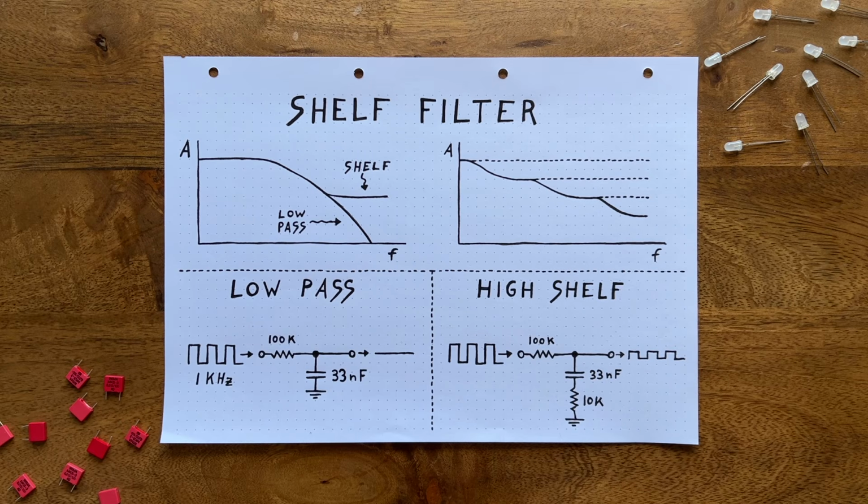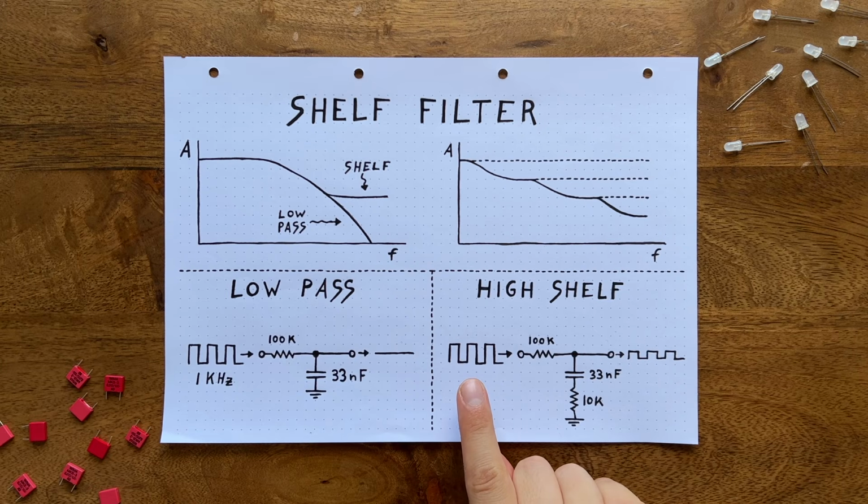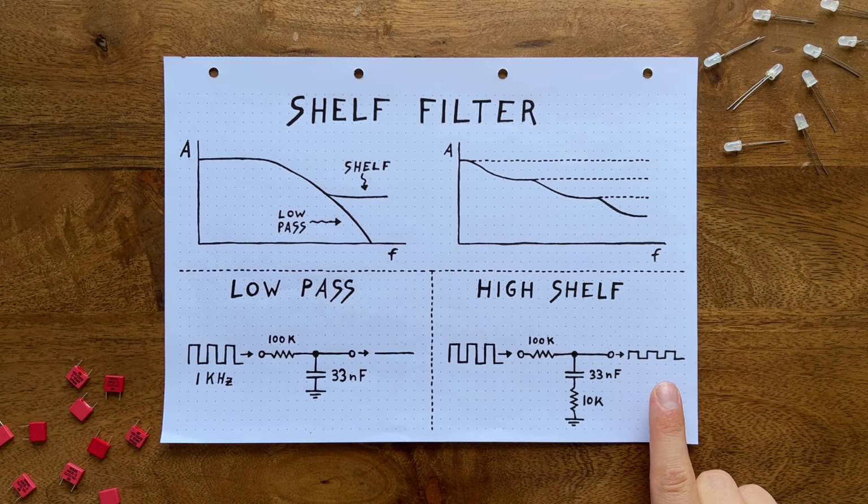...which by the law of voltage dividers must result in a significant output voltage swing, even with our super high frequency input and an almost empty capacitor. That's because the resistance on this path will go above 10K as the cap fills up, but it can never fall below that value. So as the input signal oscillates at 10 volts peak to peak, we'd pick up a significantly quieter, but definitely audible 1 volt peak to peak signal at the output. And voila, we've set an amplitude shelf that the filter's output cannot fall below.